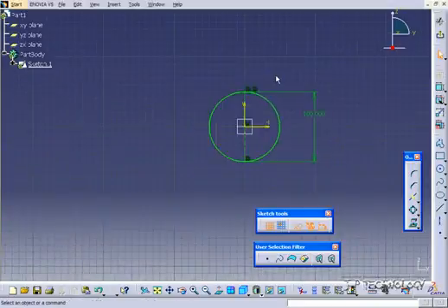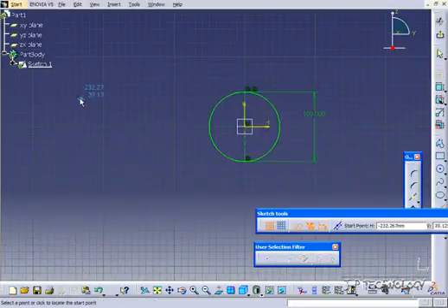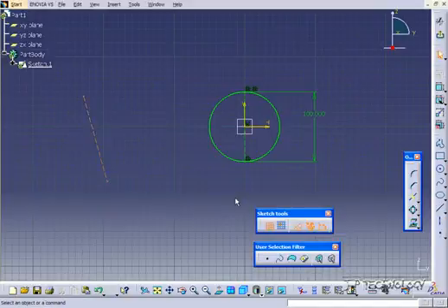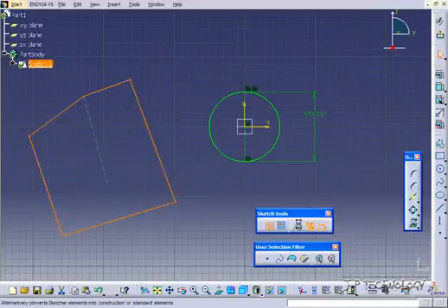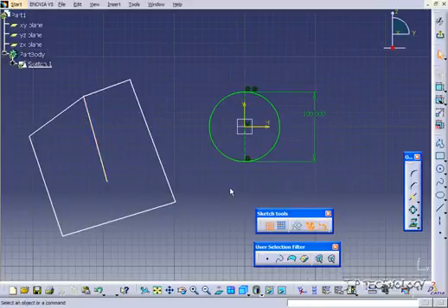So when you have a sketch or a profile, if you have a bunch of other lines that are just out at the side, you're able to use those as construction geometry. Now, you're able to either select a line and turn it into construction geometry like we did the first time, or if you toggle the construction geometry on, every profile that you make is going to be a construction geometry. So there's a couple different ways of going about it, and you can turn it back from a construction to a regular drawing.